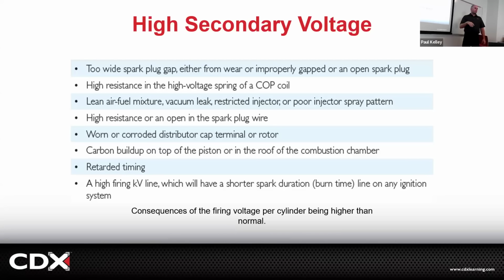Let's say it was cylinder 2. I'd look at 1, it looks clean. 2 looks carboned up. 3 looks clean. Be like, yeah, there you go. I can see the carbon in there. I wouldn't have initially checked that though. The firing line would have led me to check that. You could also do that with a compression test. Cylinder 2 compression would actually measure higher with the compression test gauge.